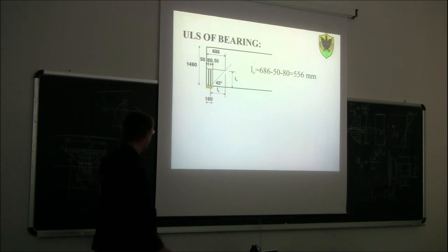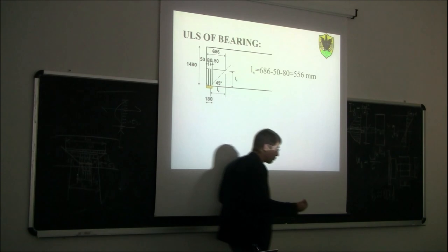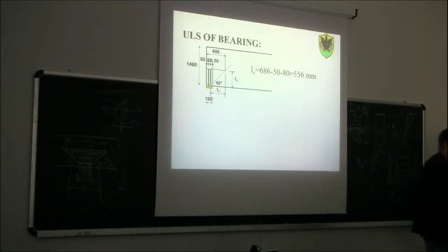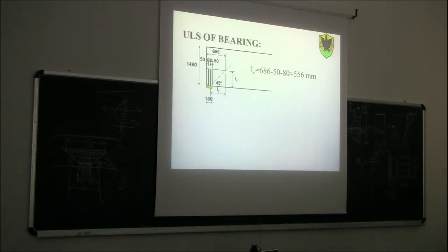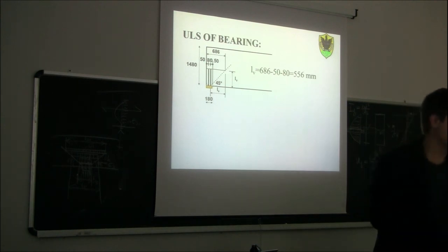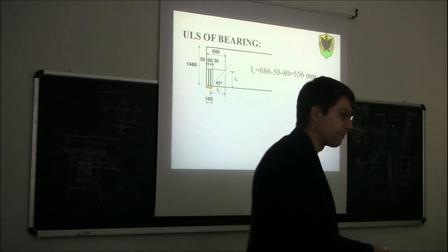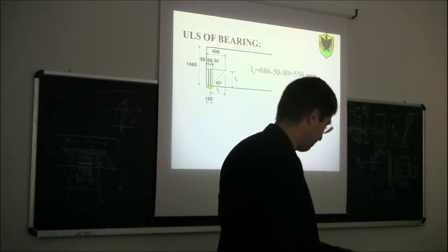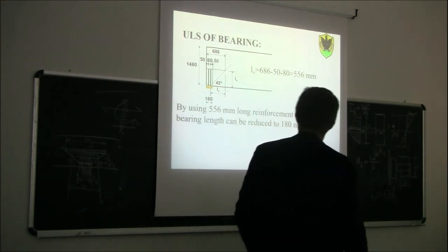Okay? So those screws will have to be designed to satisfy flexural buckling, but not the normal flexural buckling as we studied for the column, because here there is the wood, which in some way is going to provide some restraint. But this restraint is very weak because the wood is perpendicular to the grain.